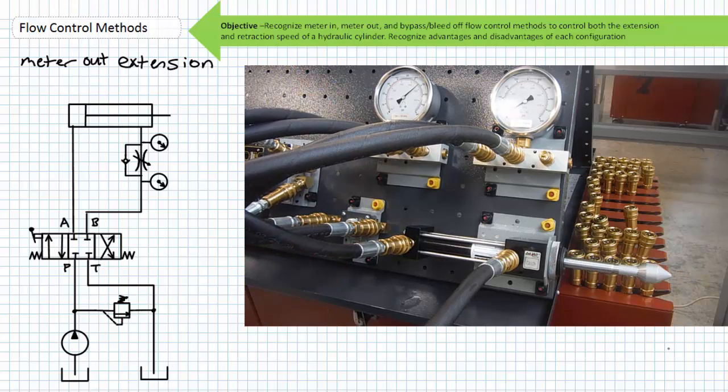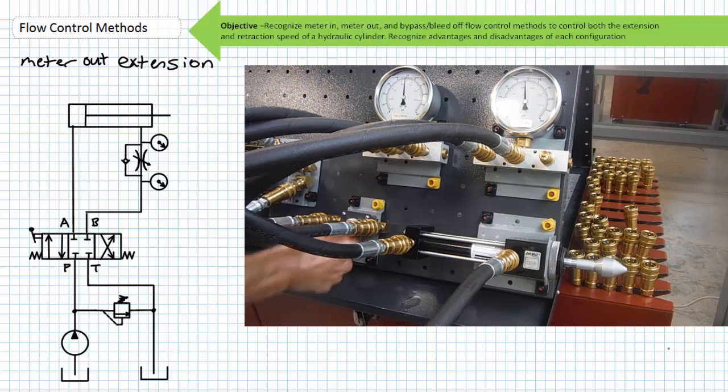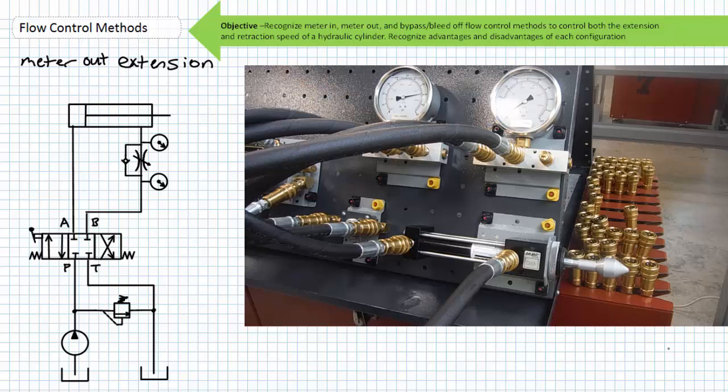In this case, pressure intensification in excess of our relief valve setting can occur because of the imbalance between our cap and rod end area. Same force, less area equals more pressure. You must take this intensification into account for components, hoses, and fittings.